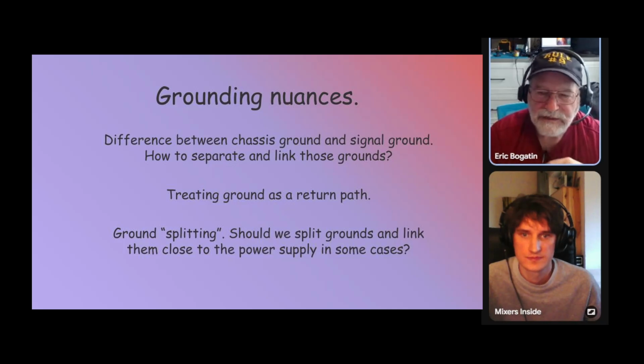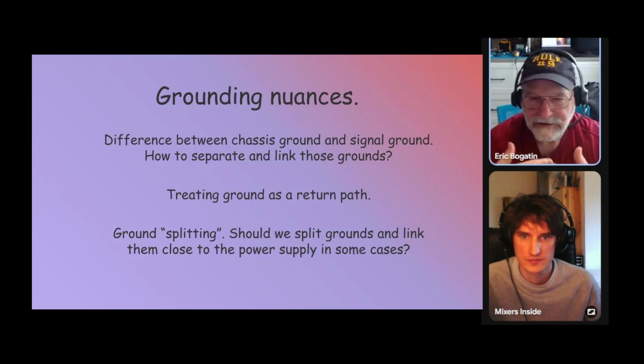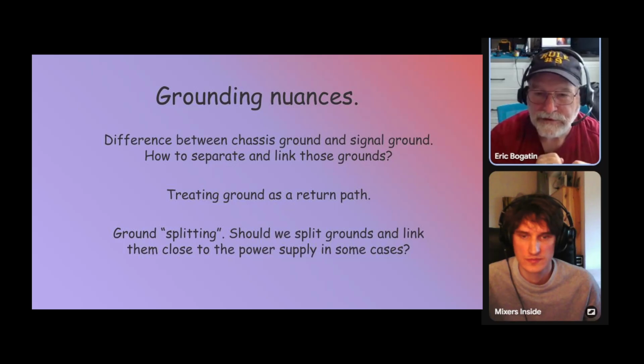And at high frequency, that return current is directly underneath the signal line. There's no resistive crosstalk. We have capacitive and inductive crosstalk between the traces, driven by the dI/dt and the dV/dt, the high frequency changing current and voltage. We have crosstalk, but there's no resistive crosstalk because there's no overlap of the return currents.